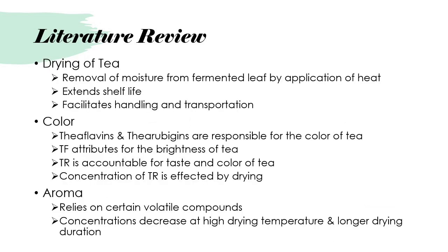Now let's come to the drying of tea. Drying is the phase in which moisture is removed from the fermented tea leaf by application of heat. The enzyme activities and oxidation come to a halt in this process, which leads us to extend the shelf life and facilitate in handling and transportation of the tea.